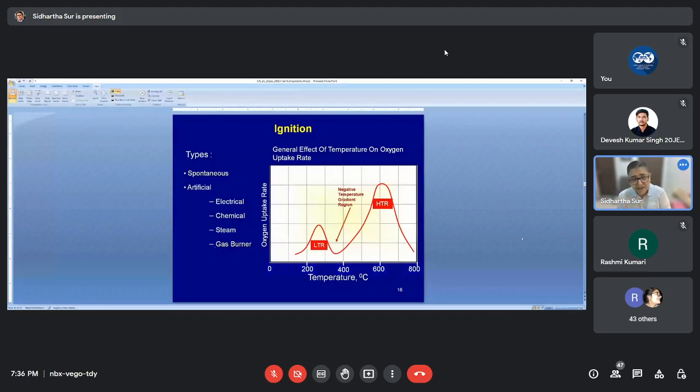So for that, you have to be very careful in selecting your ignition process, which is to the left of the slide, which ignition process you'd like to see, such that the temperature in the well starts very high at around 600 degrees C. So this is a very important curve which ensures the success of the in-situ combustion process.